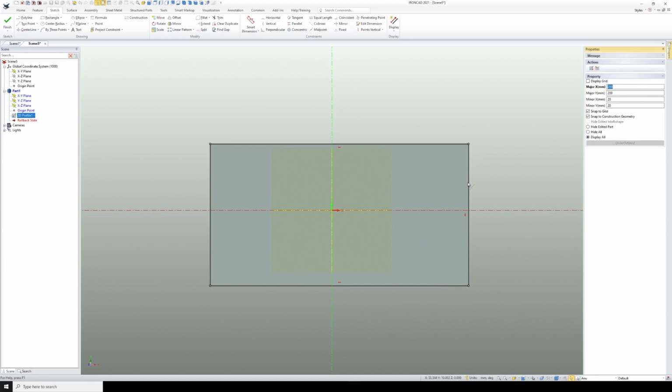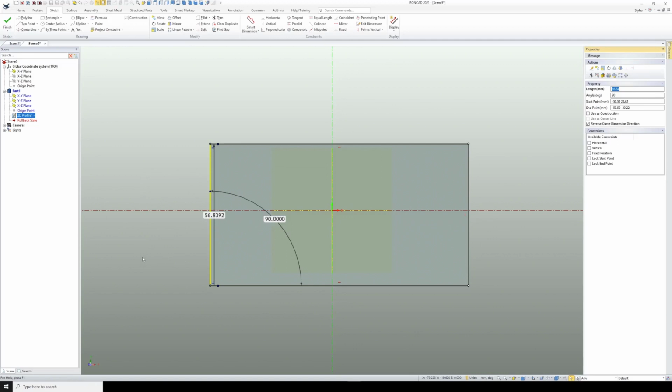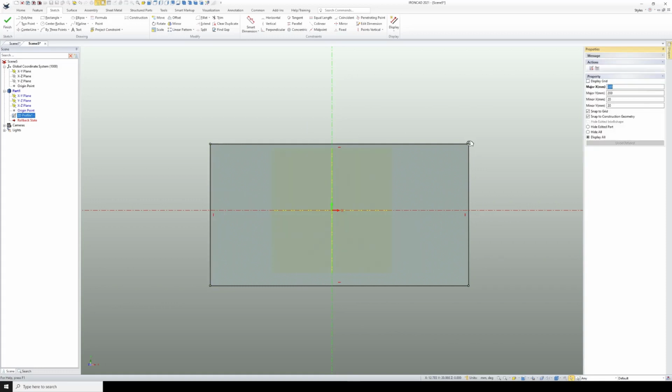Now you can select the lines individually, or you can box select. And so I'm just going to box select through this one left, just to demonstrate. Going from right to left, I'm just holding down the left mouse key to select, and then in the properties browser I'm going to set this to being a vertical constraint as well. Done. So the horizontal and vertical, I'm part way there, but I want this to be perfectly centered to the axes of the sketch as well.